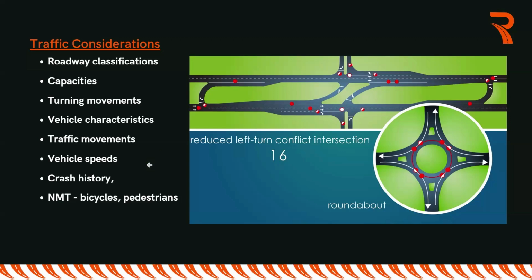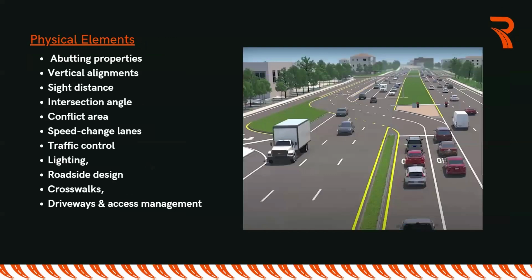And then after that, there is crash history. This is very important when you're doing intersection design. This is where we conduct surveys, origin-destination (OD) surveys, and also interrogate the road users. Where do we find most of the accidents here? Which side of the road causes more accidents? Where do we see more conflict? So that you can reason how to sort the vehicles that are moving from leg X or leg Y. And then, of course, at the end of the day, you need to consider whether I am supposed to integrate NMT, bicycles and pedestrians, in my design. And I think this is compulsory in our days.